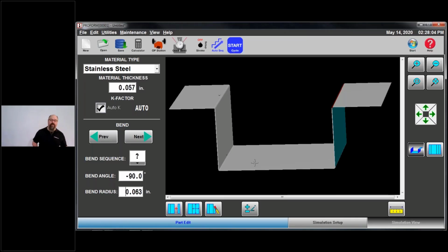A lot of my engineers will tell you bend radius is simply material thickness, not if you're using overly wide or overly narrow V openings. If you're using a very narrow V, that bend radius is going to shrink. If you're using an overly wide V, that bend radius is going to grow. Okay, all of that is determined by the lower die when you're air bending. And again, I'm not going to rehash what we went over in the previous webinar.